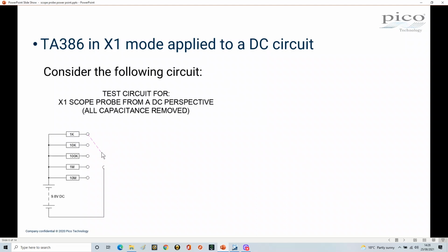And we're going to have some test equipment here in a minute. But ideally, your test equipment shouldn't change any of the characteristics in your circuit. So ideally, if this was a perfect piece of equipment, it would have an infinite load resistance, so it didn't affect your circuit. Which means that if I put my test equipment across here to ground, then because this has got an infinite impedance, there's no current flowing through here. Therefore, the voltage here is the same as the voltage there because there's no current flowing, and that's our ideal scenario.